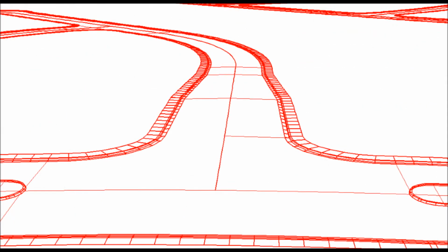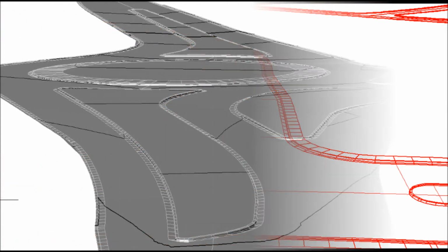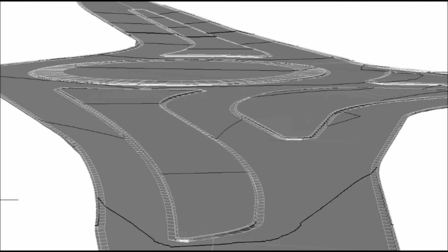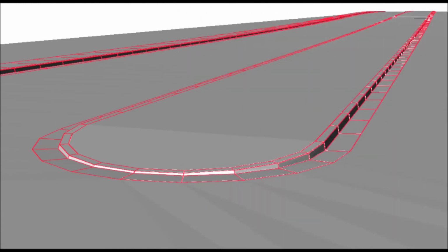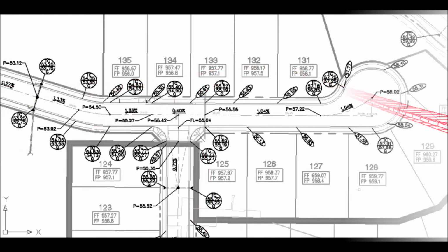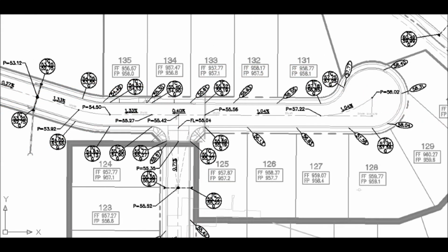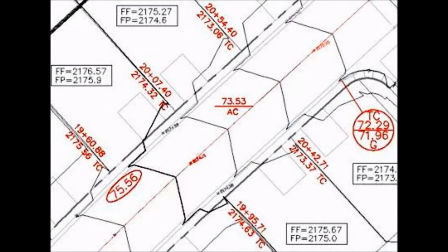All you need is a single center line and the establishment of key elevations along the curbs, and the 3D element of the design is combined with the base map control to generate the 3D road model for the top or the datum surface. So this eliminates a tremendous amount of time in your design work. And in the production, you see the same benefit because the true length and true grade calculations are also performed by referencing that base map control data.